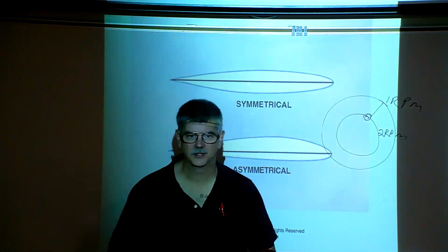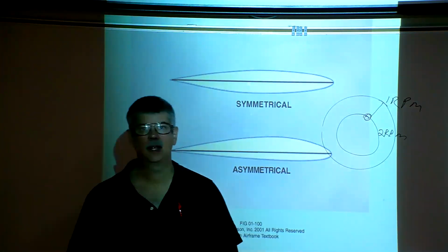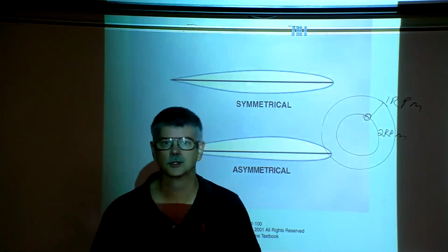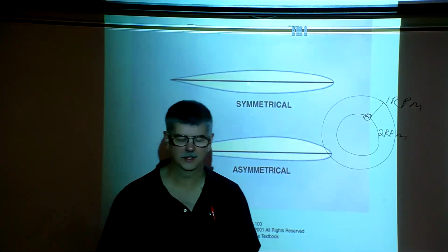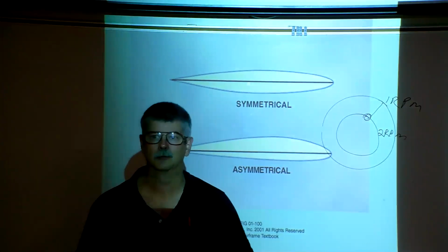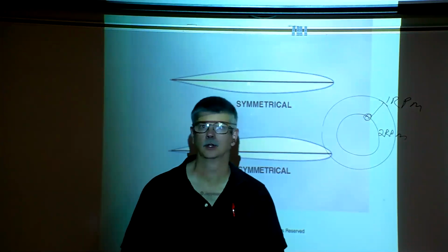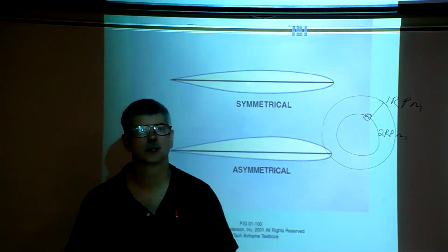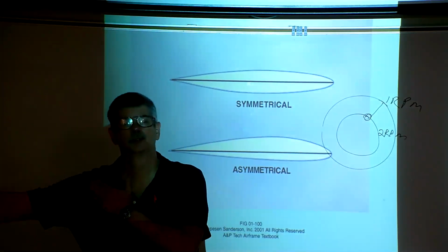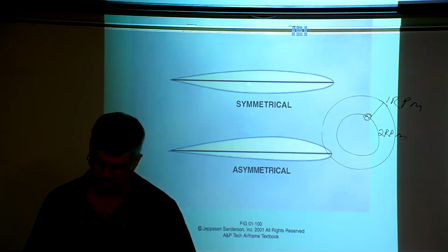A semi-rigid rotor blade is designed to be underslung so that it minimizes this effect. A fully articulating rotor blade doesn't try to minimize the Coriolis effect. It has a lead and lag hinge so that the blades can move forward and aft.